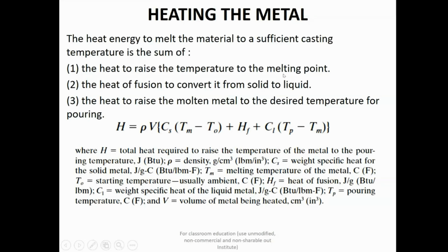So how can you calculate this heat? This is calculated with the help of this component, which is rho v. Rho v is your mass. So m c delta T, if you remember it from your thermodynamics, is the heat which is required to raise the temperature to the melting point. It can be calculated with the help of m c delta T. Here this C is your C_S,